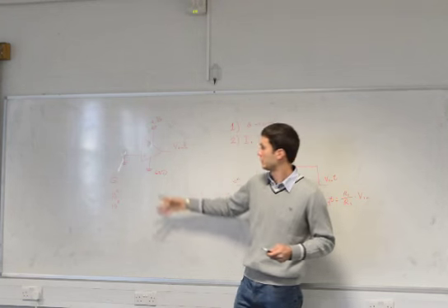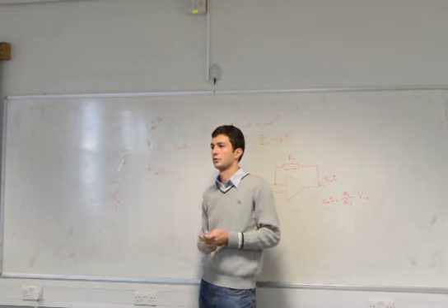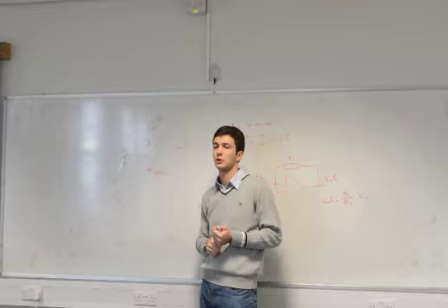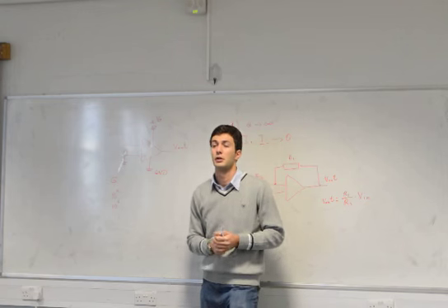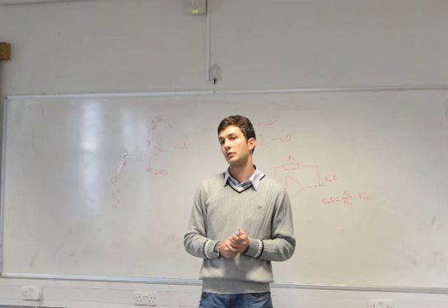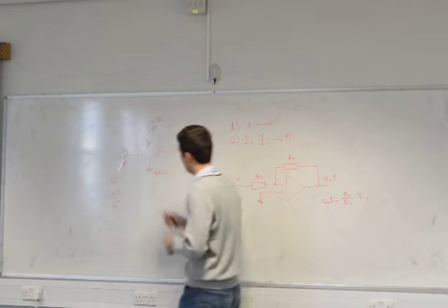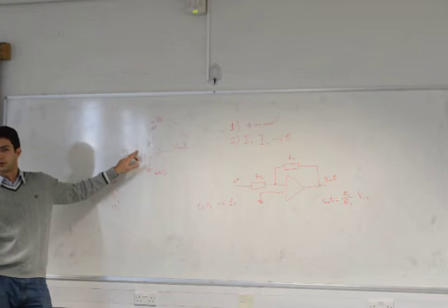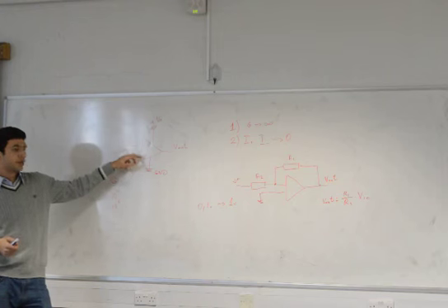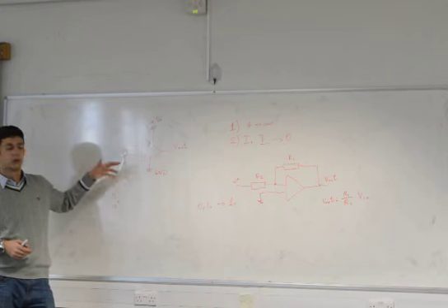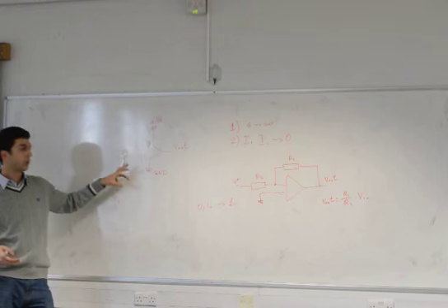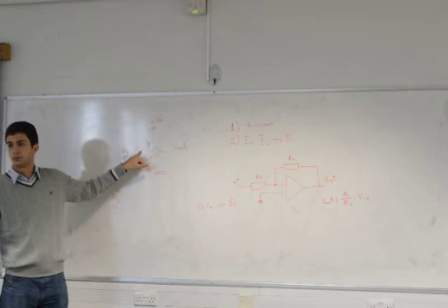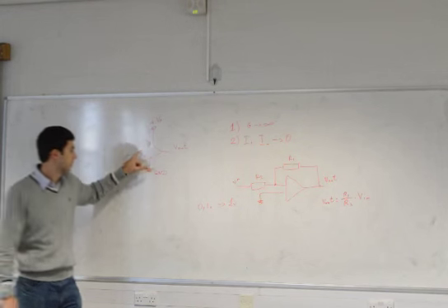Why do you think it's important that these input pins don't consume current? Any ideas? Why? It's because when you amplify at the other end, it won't be in the right ratio or something? No, because if we have a current flow here, if we have a very low voltage here, like 0.05 for example, and there's current, it will get even lower, and it will affect the whole system. So we want to keep the potential we have here. So maximum input resistance will just not pull this down.